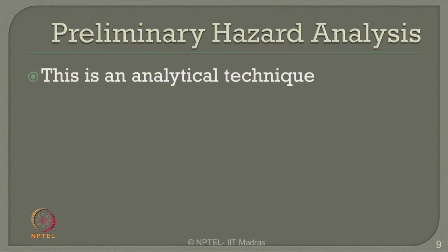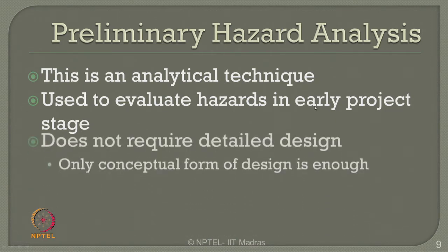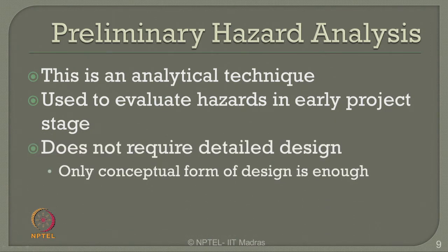When we talk about preliminary hazard analysis, because any analysis has preliminary and detailed stages, let us talk about preliminary hazard analysis. This is an analytical technique which is used to evaluate hazards in an early project stage. So, preliminary does not refer to the hazard; it is only the stage of the project which is early, therefore, it is preliminary. It does not require of course any detailed design, only a conceptual form of design is enough to carry out preliminary hazard analysis.